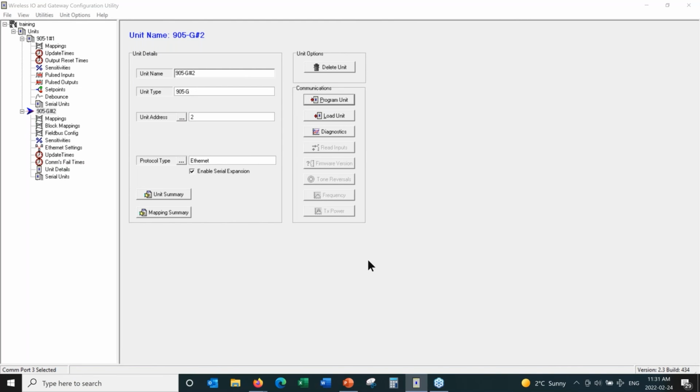If I look at the TX and RX LEDs on the radio, I can see there is activity there. And what I have is two small whip antennas. These antennas are about 5 inches tall, and I have attenuators in series with both antennas. That's because these two radios are just side by side. Otherwise there would be some issues. They would essentially be saturating if we didn't have attenuators connected, and we may lose radio communications between them.